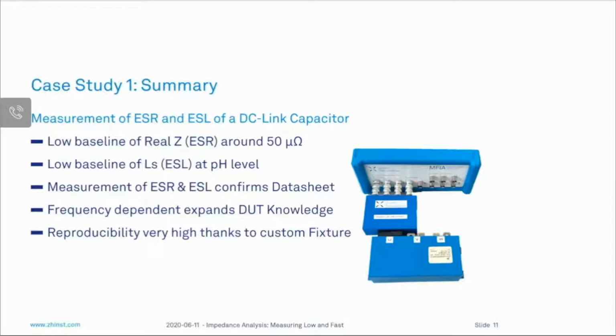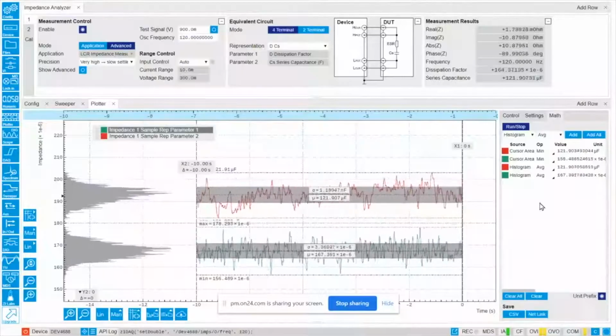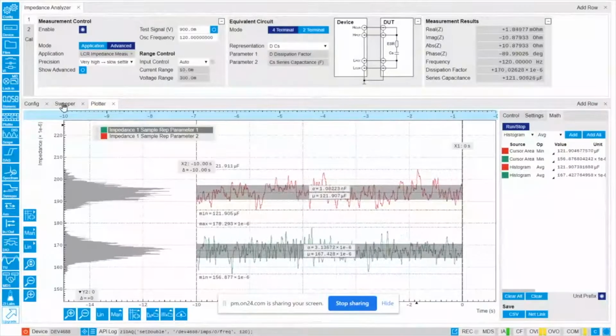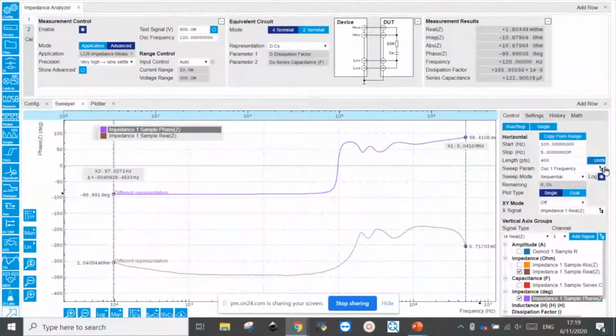All right. So let's start from a question from Mary. How can you save the data from LabOne? Right. So let me go back to the sweeper view. And here, let's say you've taken your sweep, and then you can either save it as text, directly from this view, or you can save it as, for example, vector graphics.